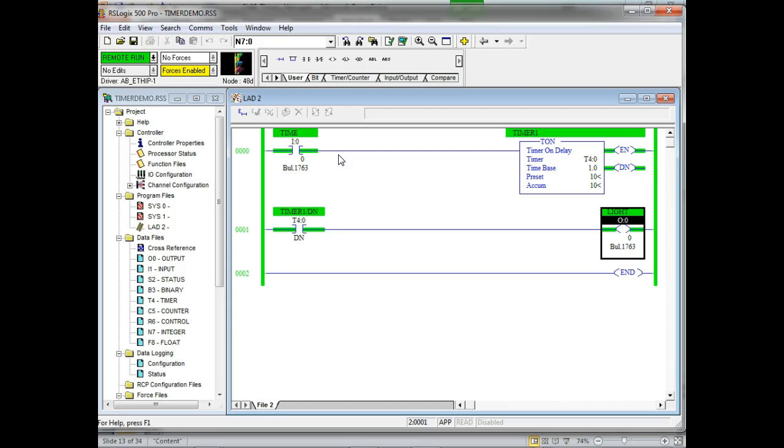Which means, like I said, this is a single input timer. So that one input is not only telling it to start timing, it's also a reset. That makes sense? Pretty neat. So we can go any value up to 65,535, right? You understand? 65,535 because it's a 16-bit number. If I need something longer than that, I can cascade it. So I can use the done bit of this one to do what? Start the next timer. So we could time for a year.